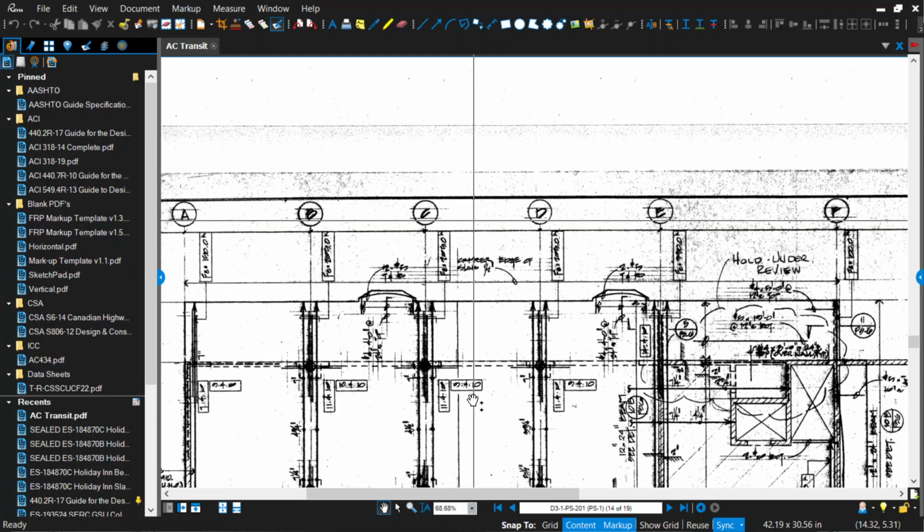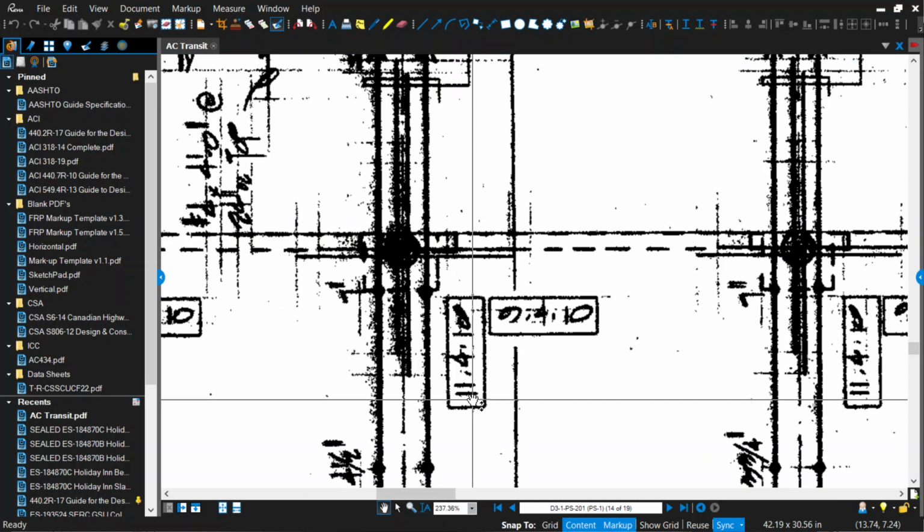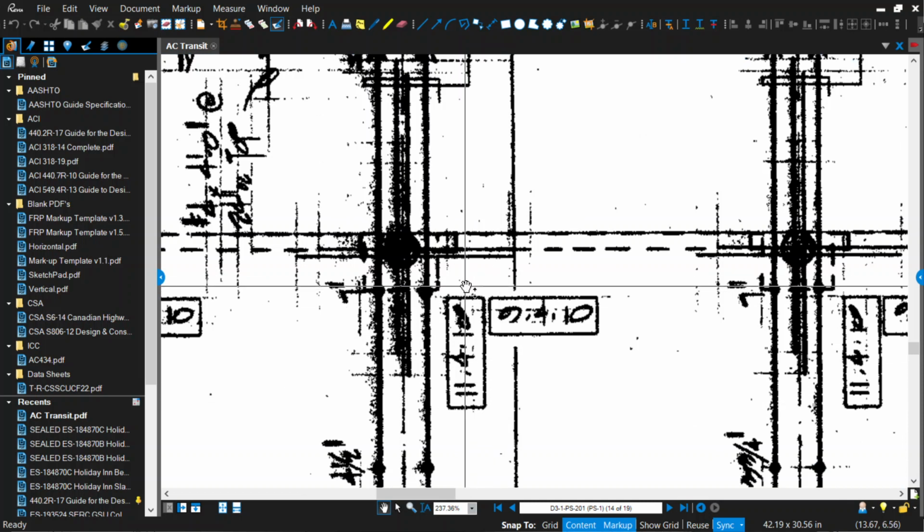When they show those bars, that's the length of the bar. Yeah, so the rebar provider who's providing bars to go to the job site looks at this project and knows he needs 9 number 4s by 10 feet long over this column, and so they're exactly 10 feet long. Okay. But when we're doing rebar equivalency, we're not matching drawings that show what rebar was supposed to go in the slab, right? Typically.